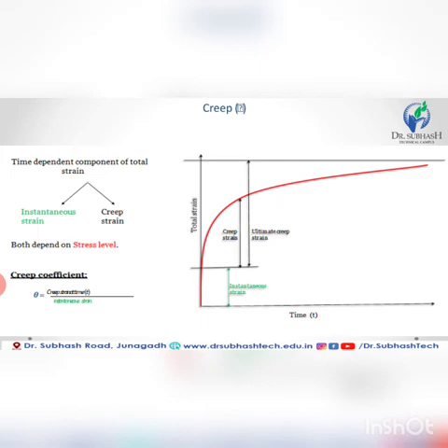Creep. Time dependent component of total strain. Two types of strain: instantaneous strain and creep strain. Both depend on stress level. Creep coefficient theta is equal to creep strain divided by instantaneous strain.